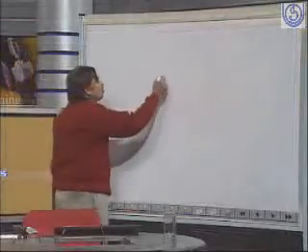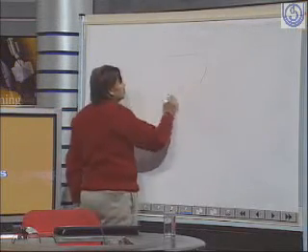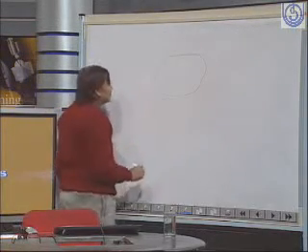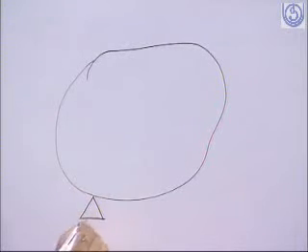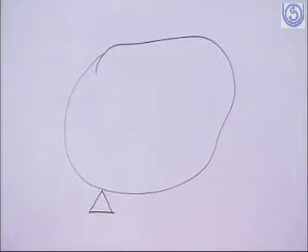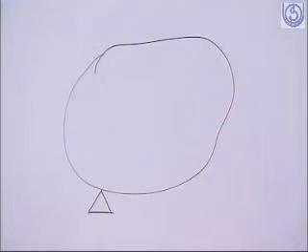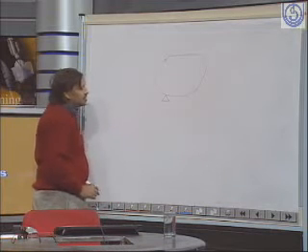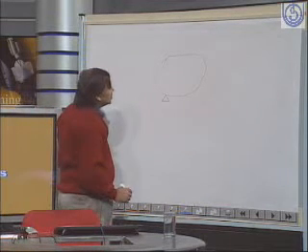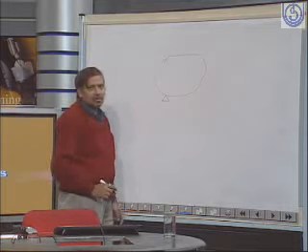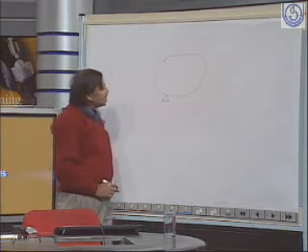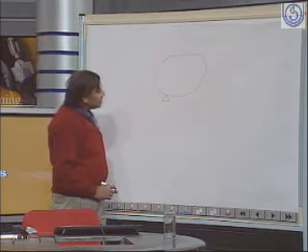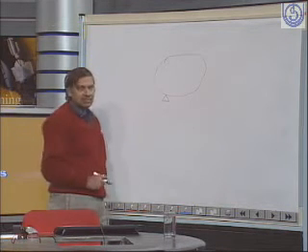So the reaction component, what does it mean non-trivial? Let us see the thing in a plane structure. When you come to a plane structure, then only 2 directions are important, x and y direction, because the x and y plane is important, and a rotation can take place in that plane about the z axis.